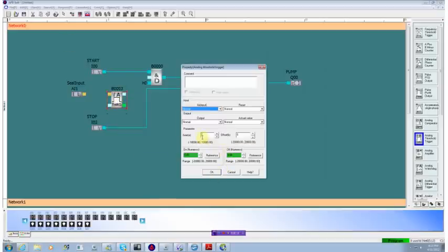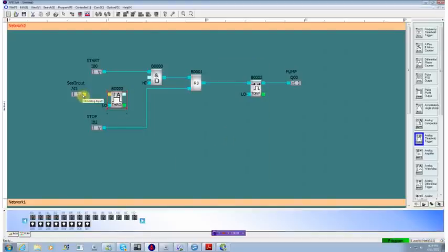we see that first of all there's the ability to apply a gain and an offset so we can linearize the signal somewhat. We have a reset, which again won't be used in this particular application. Then we have an on threshold and an off threshold. And the function will behave slightly differently depending on how we set these values. To try it out, we'll first of all set the on threshold to 5. And we'll set our off threshold to 7.5. We'll save that. We'll connect our analog input to the input and our digital output up to our AND gate.